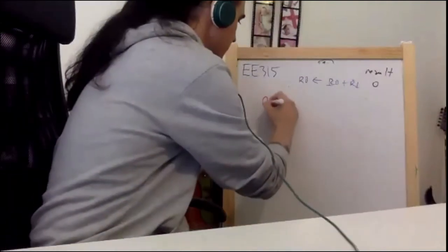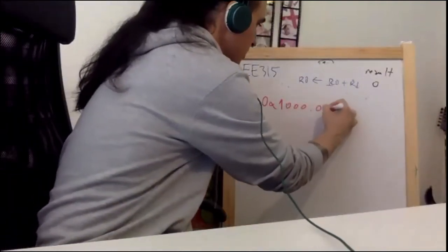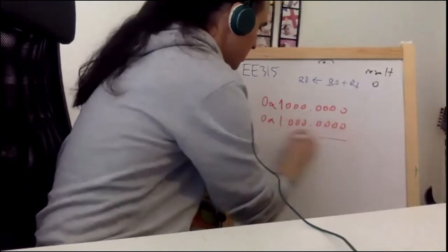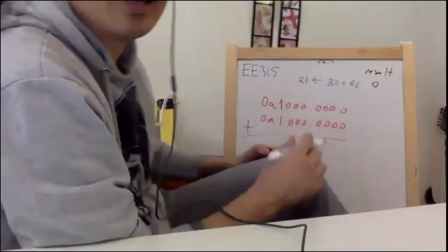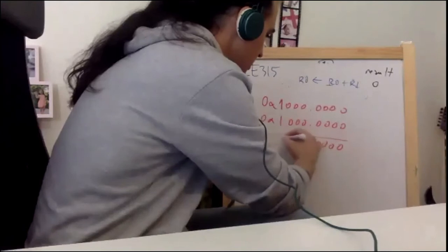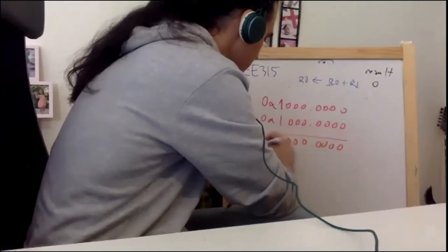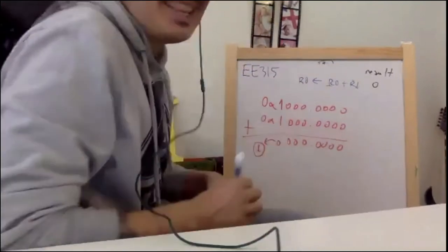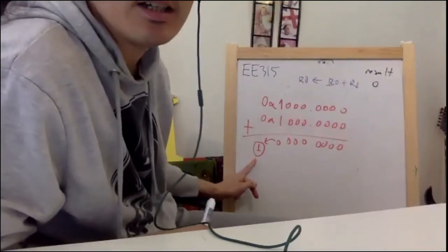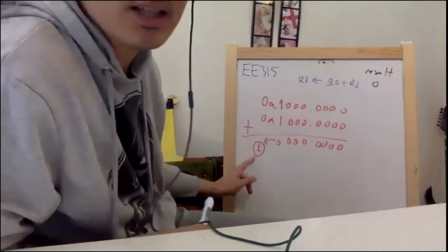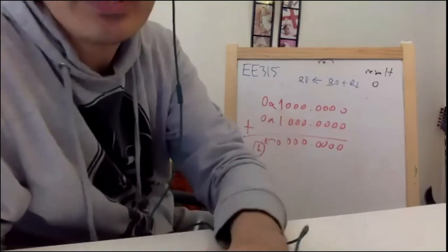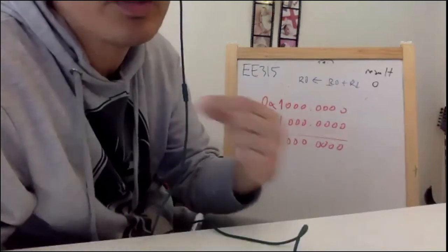So this is my number, right? Well, I'm assuming that this is an unsigned number. I'm summing the numbers. The unsigned sum makes 0 with a carry. Guys, if I assume that this is an unsigned number, I call this carry. Okay? That's why in the slides, the C bit, carry bit, becomes 1.